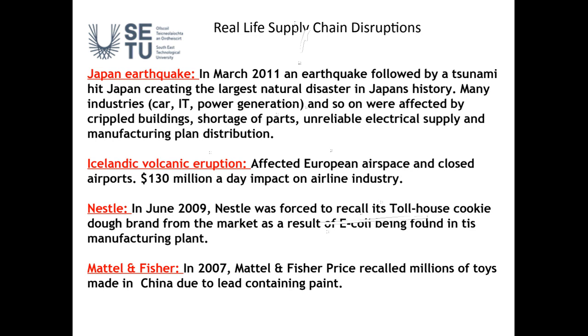If you go out in a forklift which doesn't have the equipment, it doesn't pass the safety check, and you have an accident, you will be liable, not the employer. Because they'll say, why didn't you report it? And you shouldn't have driven it if it was broken. And did you know the light wasn't working? Or did you know the brakes didn't work or whatever?